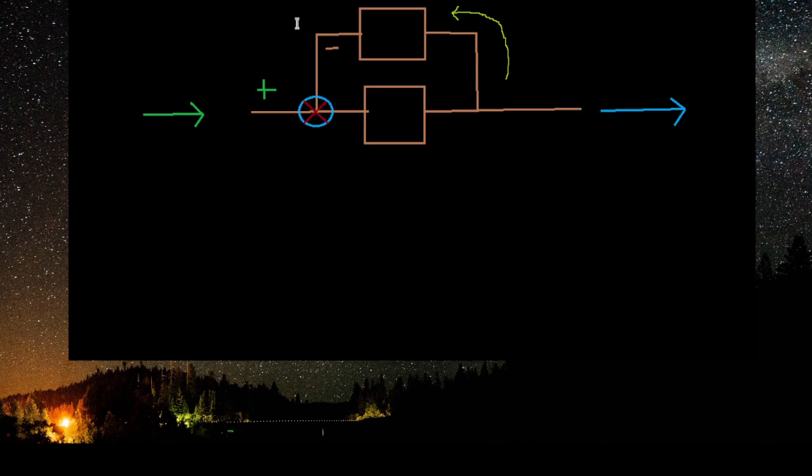Effective gain. A lot of this stuff we can just do by trial and error, but I'm wanting to, there's lead lag networks, which is your capacitor. Lead lag network capacitor, separate lag network and a lead network. Lag compensation prevents an increase in gain to reduce steady state error, while lead compensation permits an increase in response without loss of stability. Well, they talk about stability and stuff, but I'm not finding what I'm looking for.